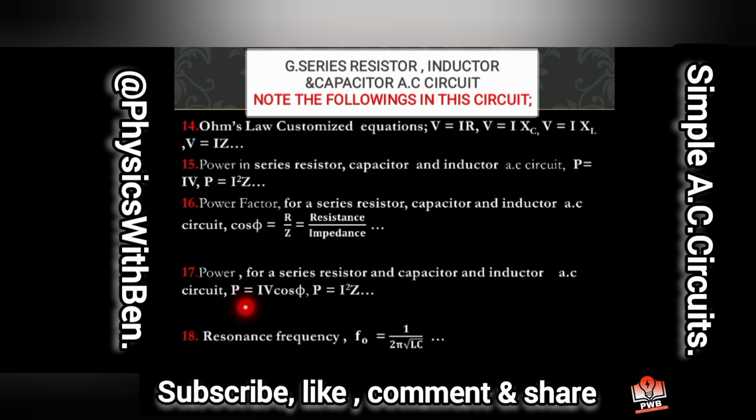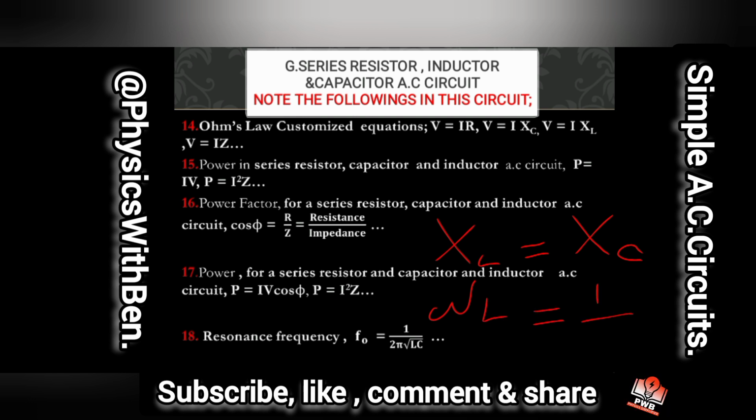And then in this circuit, you'll be asked to calculate the resonance frequency. I told us when resonance occurs. Resonance occurs in a simple AC circuit when XL is equal to XC. That is when omega L is equal to 1 all over omega C. That is when resonance occurs.